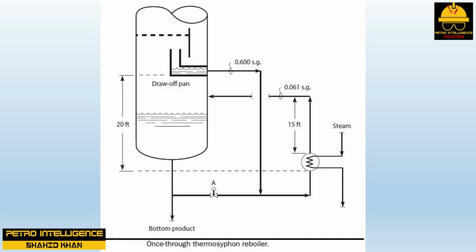temperature. Opening the steam or hot oil inlet heat supply valve does not seem to get more heat into the tower. The typical causes of this problem are bottom tray and tower leaking due to a low dry tray pressure drop. Bottom tray, seal pan, or draw-off pan is damaged.